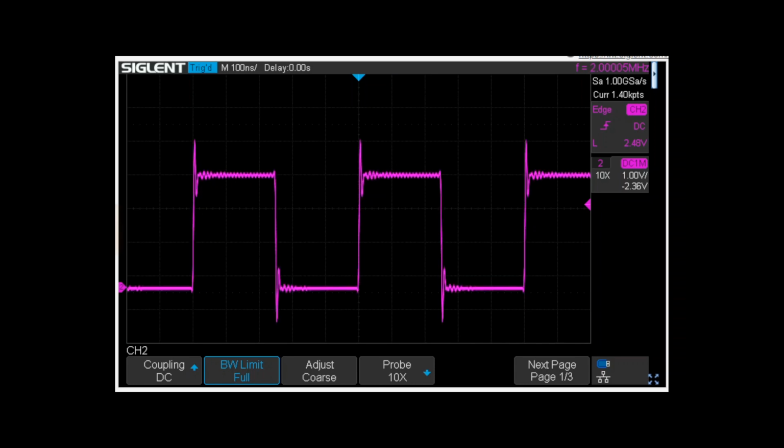And now, presumably, the rise time is faster, and it's feeding quite a bit more high frequency energy into the system, and that's stimulating the ringing, probably caused by that ground lead. So this is not a good way to measure rise time, because the signal distortions here, I think, could impact that measurement. So we'll find a better way to probe.